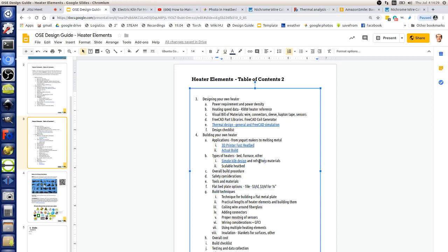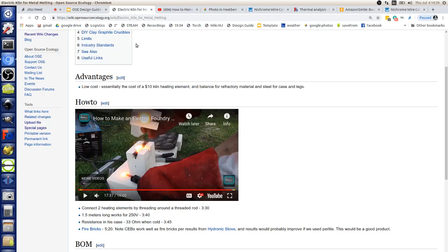When you're playing now with these kilns, this is where safety becomes pretty important, because talking about molten metal, you've got to watch out for that, and this is where you have to start wearing a bodysuit and gloves and whole face protection, because if you have any droplets of water get in there, say you put in a wet piece of metal, that's calling for explosion.